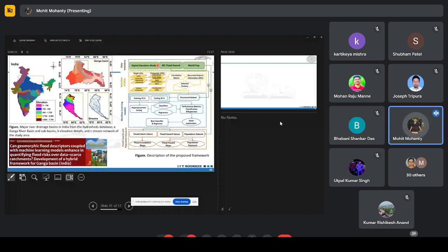We just considered the digital elevation model. The topographic data gives a lot of other information also, for example in the form of slope, elevation, the tangential feature. So a lot of indicators are embedded within the topographic data, which will give us some idea about the existence of flood lines. That is how we studied. We did some kind of training and testing based on an existing flood inundation map, and after that, we also did the Shapley analysis.